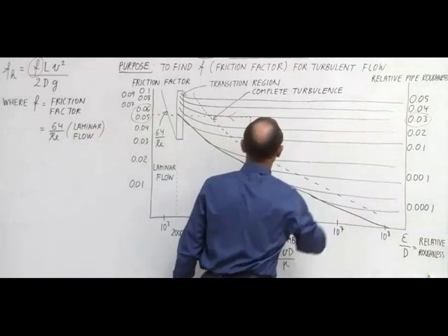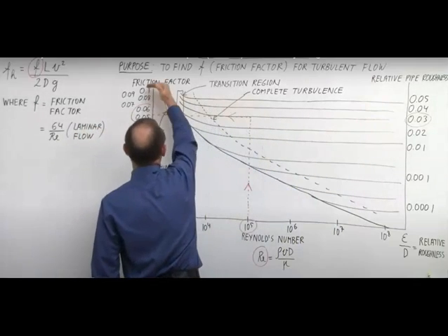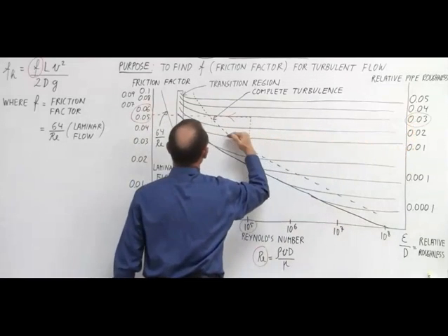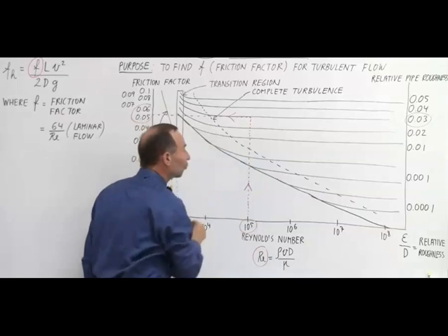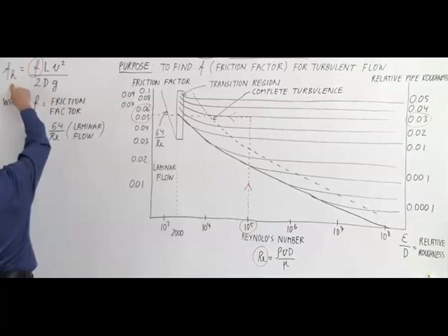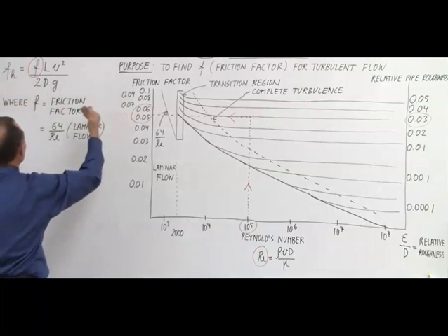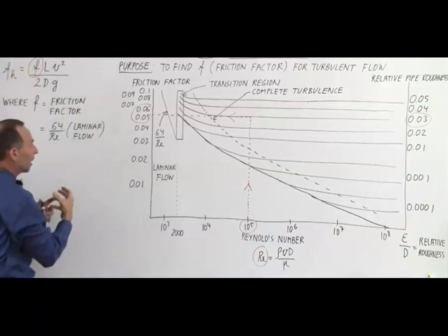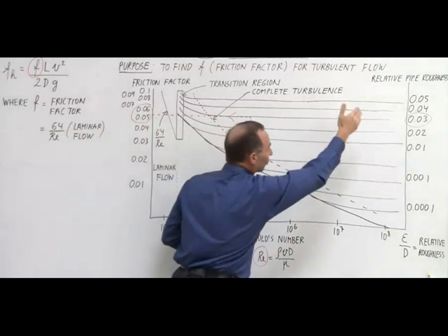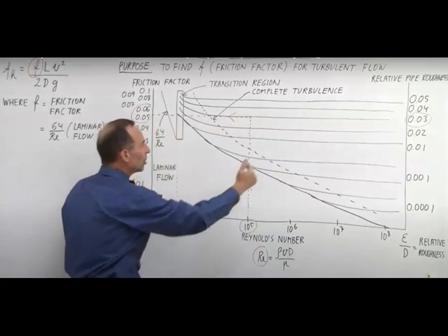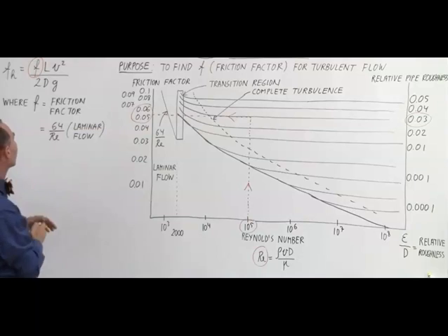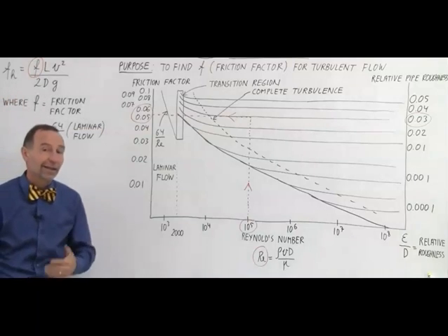Notice that if the relative roughness of the pipe is greater, then yes, we would expect a greater friction factor. If the relative roughness of the pipe is not as big, then we expect a smaller friction factor. And of course, a smaller friction factor gives you a smaller head loss. A greater friction factor gives you a greater head loss. And it all has to do with the Reynolds number and the relative pipe roughness. And on the Moody diagram, we're then able to find the corresponding friction factor necessary to...